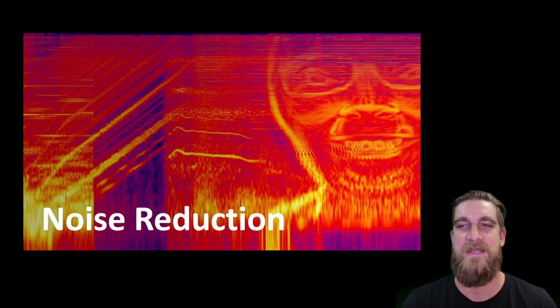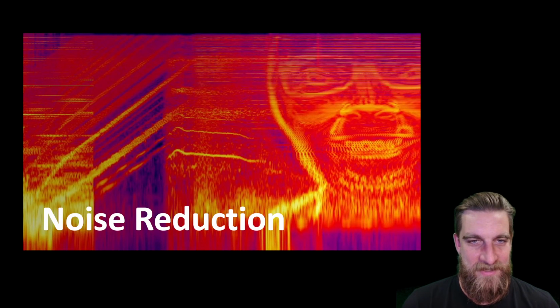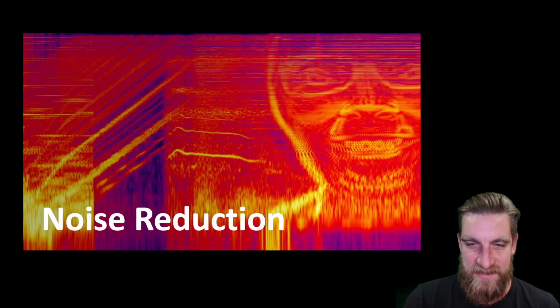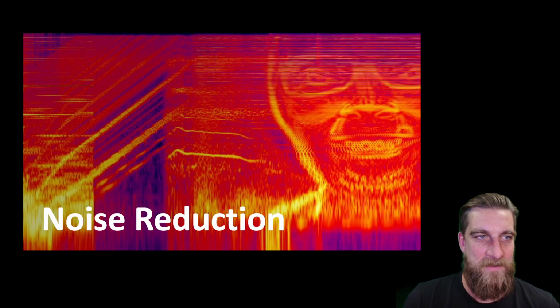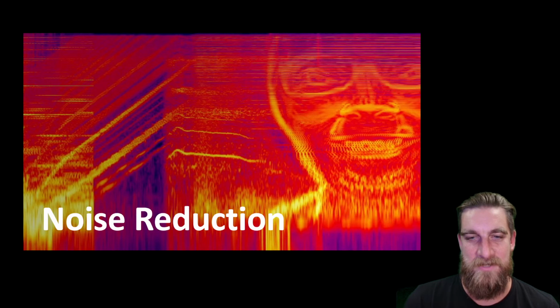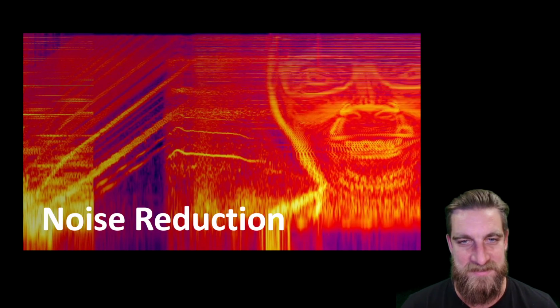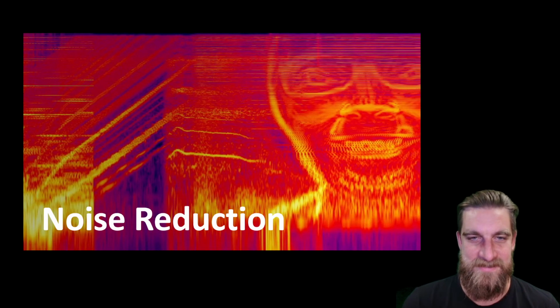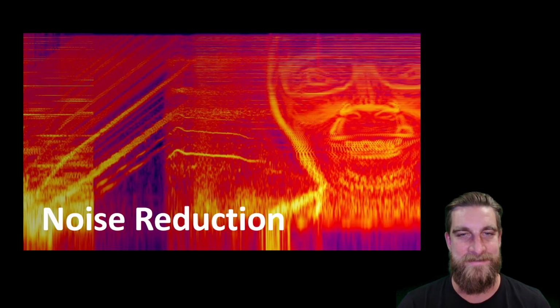Last thing on my list is noise reduction. And what you're looking at on the screen here is a picture of a spectrogram. What this is showing us is on the x-axis, from left to right, we're looking at time. And then we're looking at frequency range on the y-axis, right? So 20 hertz on the bottom, low frequency sound, and 20 kilohertz on top, the high frequency sound. And then the brightness of the image is the intensity of those frequencies at that moment in time.